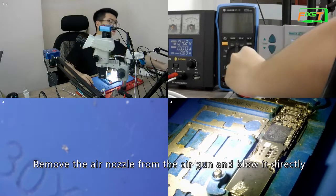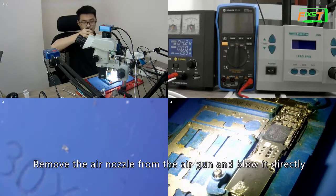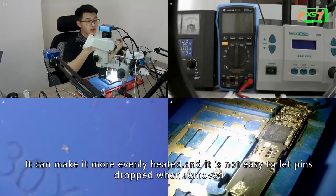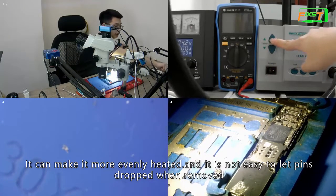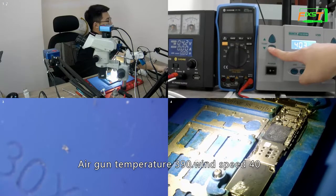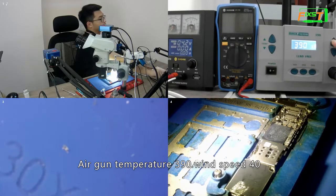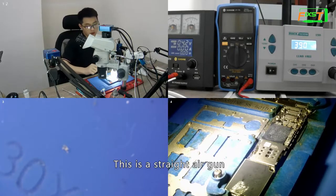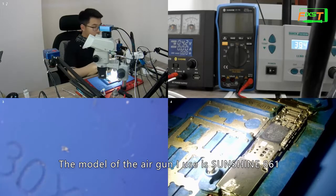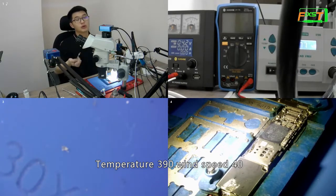Remove the air nozzle from the air gun and blow directly. It can heat more evenly, and it is not easy to let pins drop when removed. Air gun temperature 390, wind speed 40. This is a straight air gun. The model of the air gun I use is Sunshine 861. Temperature 390, wind speed 40.